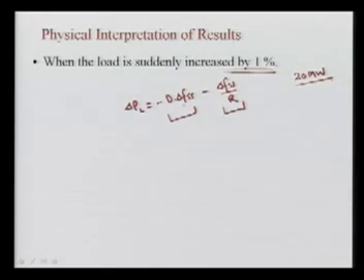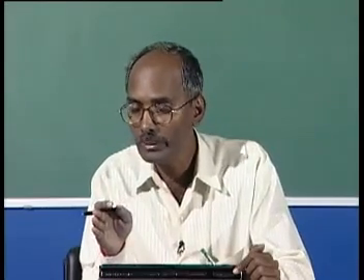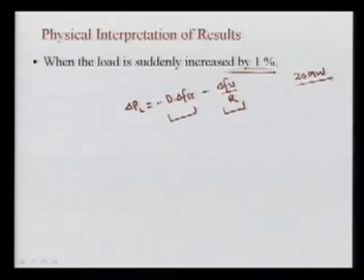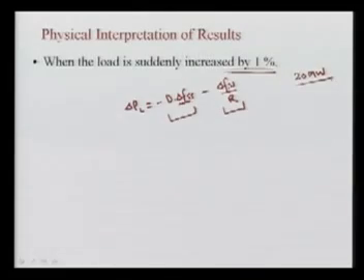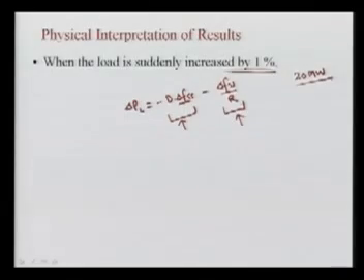So whenever there is a change in the frequency, for the first few milliseconds there will be no change and the kinetic energy will be supplying this load release, this demand, and then frequency will of course fall. Once there is a fall, meaning there is a change in the steady state frequency, then we will get the net load released by the load components, and here the governor will come into action and it will try to provide power.